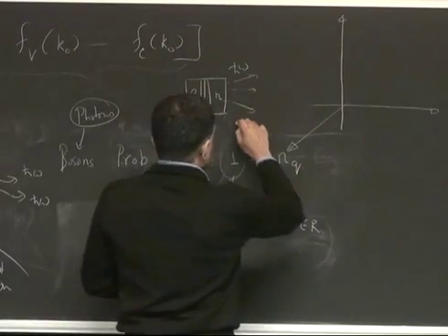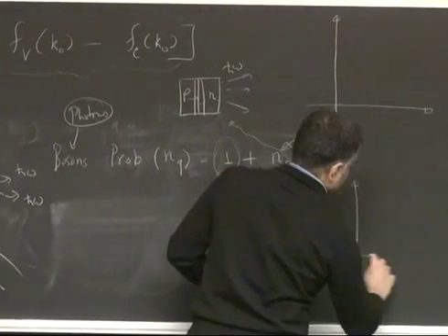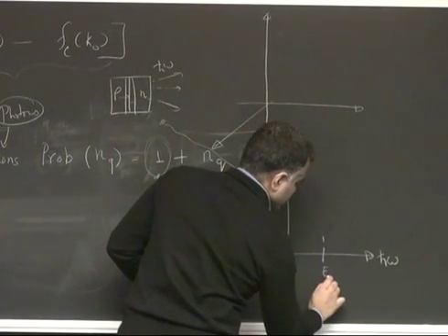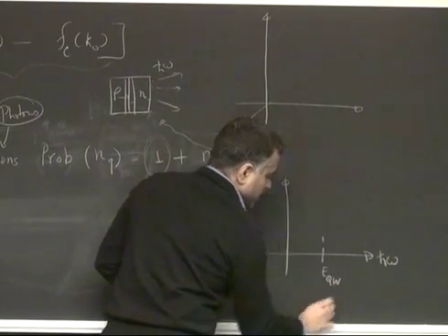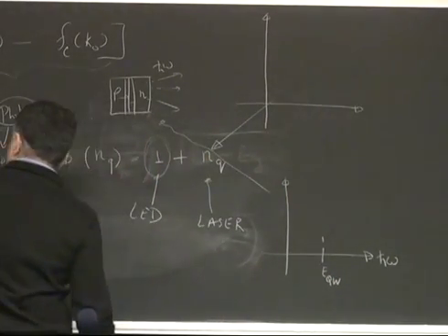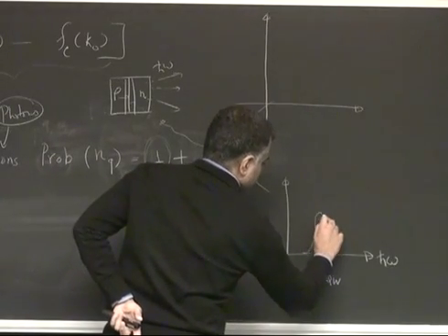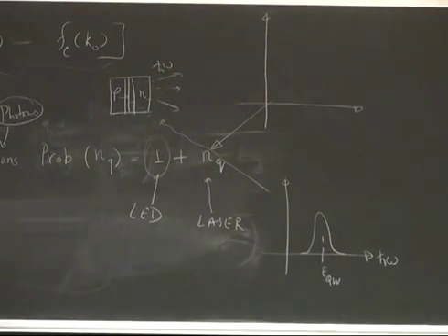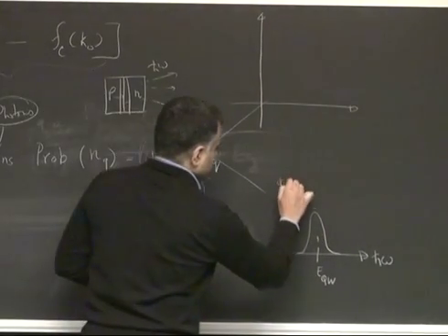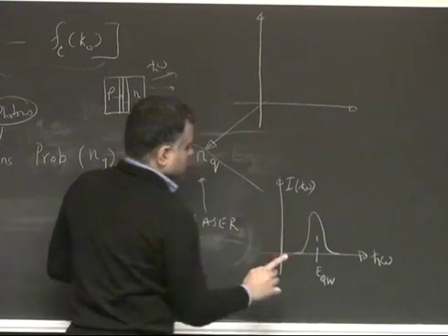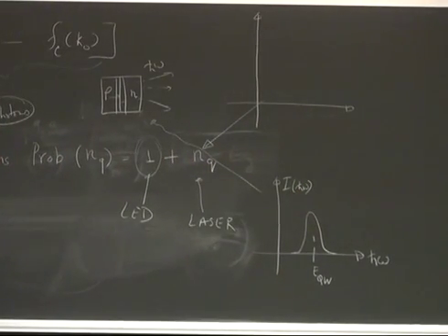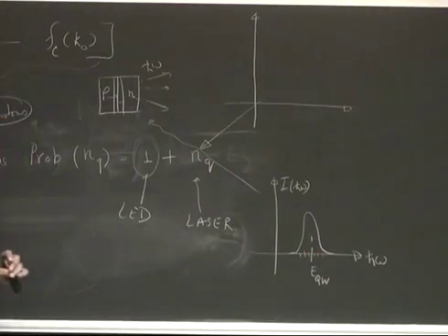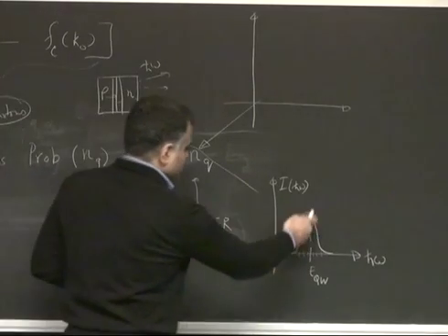And when it emits, the spectrum over energy is going to look, let's say this is what you have designed of the quantum well interband transition energies, the spectrum will look something like this. So there will be some broadening. So this is the intensity of output of photons. Not just in energy, so it's obviously broadened in energy, with a peak at some point.